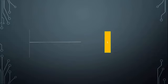Thus, when power is positive, the magnetic field is being built up by the inductor. A moment later, when the power is negative, the energy in the magnetic field is decreasing and flowing back to the source. When you have your negative peak, the power stored by this inductor is released and that energy flows back to the generator.